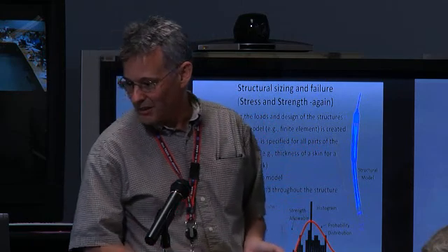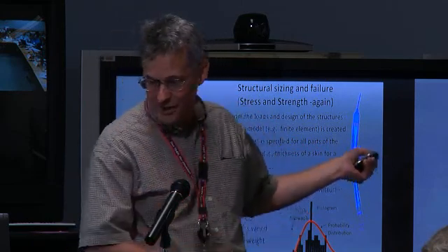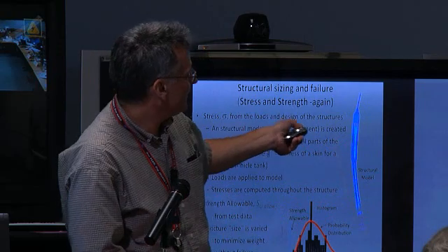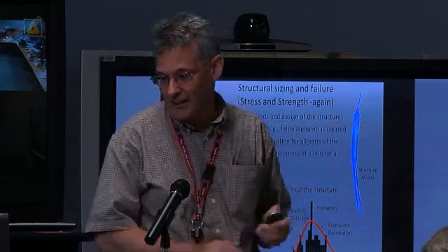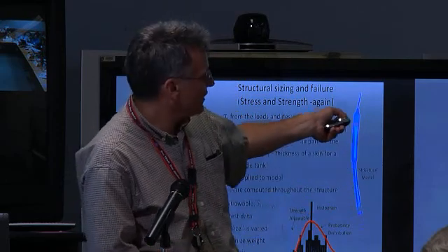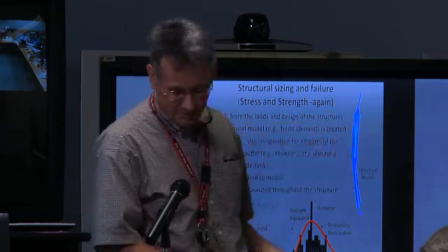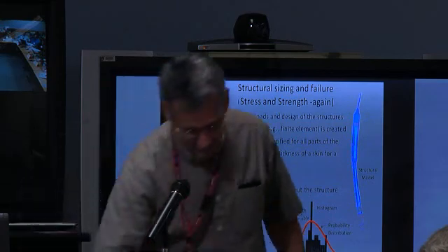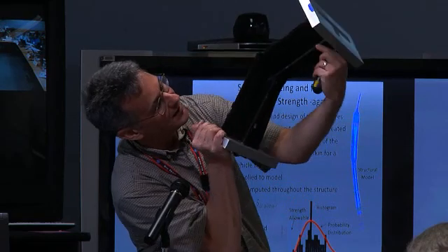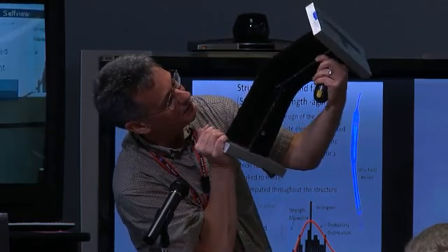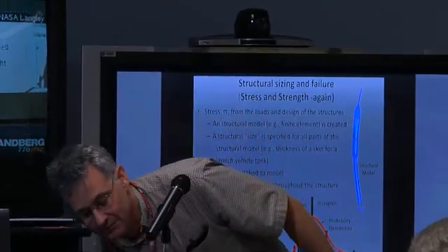Okay, I got part of this cut off here. Basically, the stress due to the loads comes from a structural model. I mentioned that. You've got a structural element model, and that's used to determine the thicknesses of all those pieces of structure. If this is a piece of a structure, what's the thickness of this skin there? What's the height or diameter of this little rod here, this cross section? All those pieces all over your vehicle are designed to be the most optimal possible, to be the most weight efficient.